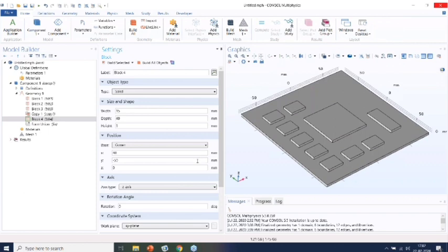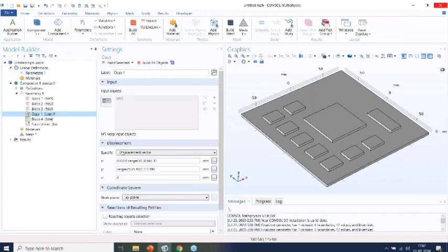Yeah, on build selected, an incompatible length of displacement vector error is coming. Please check that you have provided the complete displacement vector as I have mentioned over here. That is 0, 0, 0, 0, 4 zeros, then range 30, 30, 60 and 30. This is the x displacement vector, and corresponding to the length of the x displacement vector, you have to provide the y displacement vector as well. That is range equal to 25, 25, 100.